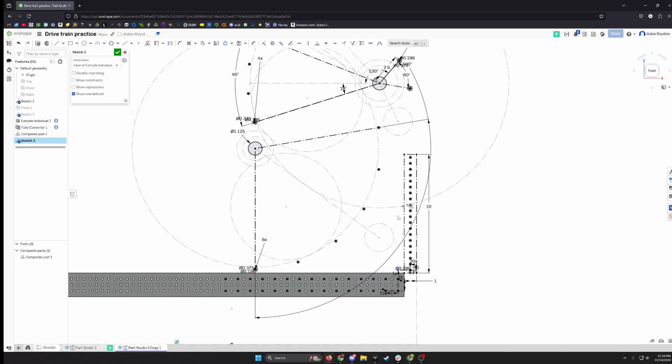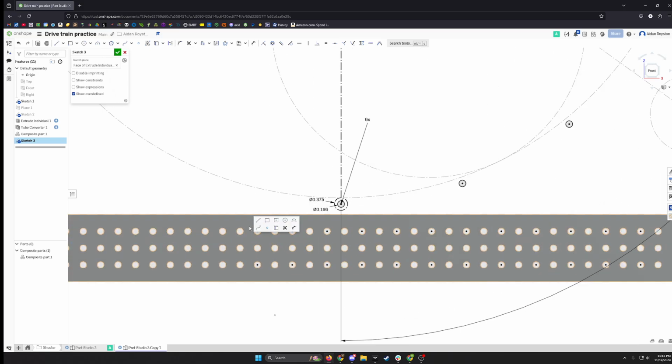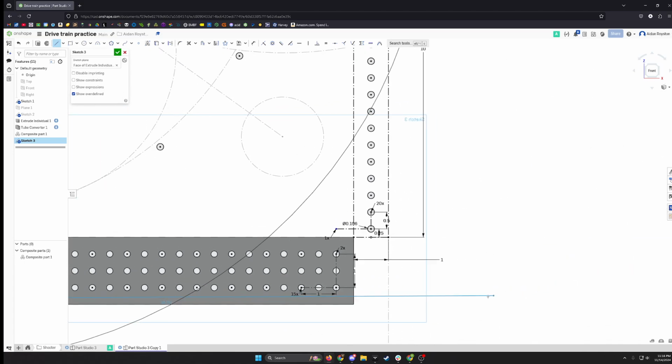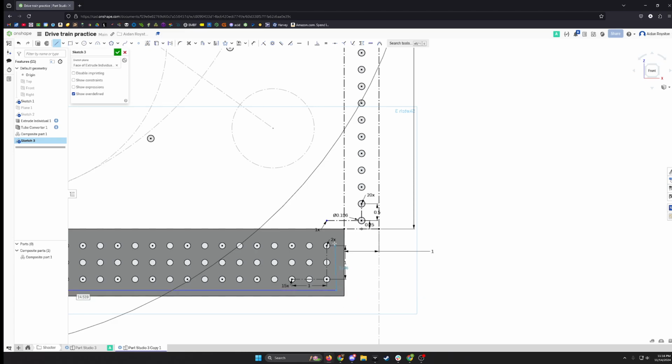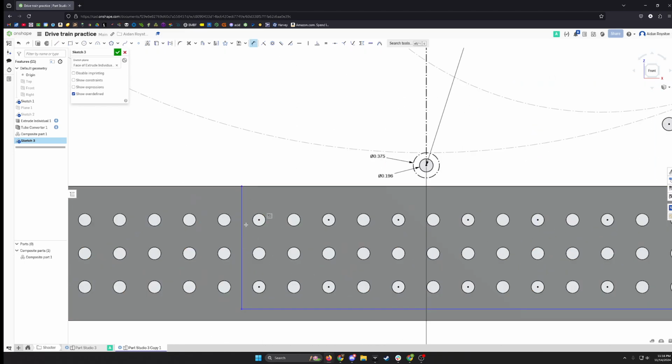So now we have most of the features here. We can go ahead and start drawing the outside profile. We'll just start that down here. You can just start it at this line, bring it down, just across. We're just going to get the general shape here, and then we'll get some dimensions in a second. So we have this line, and it's all blue. We're going to want to dimension this from the center point of this first hole about 1/4 inch, and the same down here.